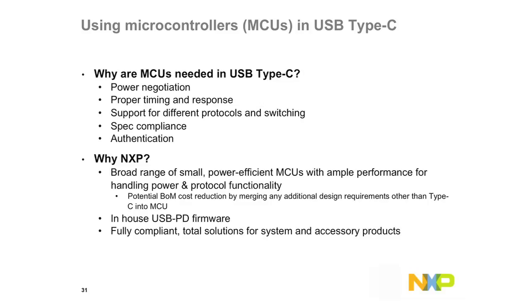And you can think of a microcontroller as a resource that you could leverage to not only achieve the base Type-C functionality, but also to add on extra functionality that may or may not be required, like authentication. NXP also has in-house USB PD firmware that's fully compliant, and it's very configurable in order to achieve a use case for a system and an accessory.